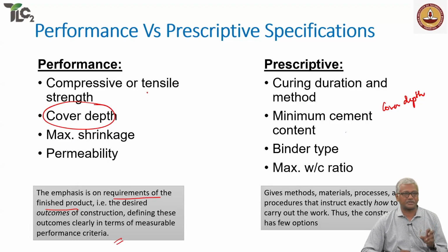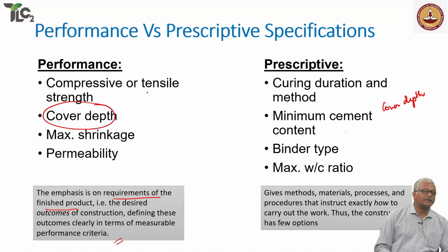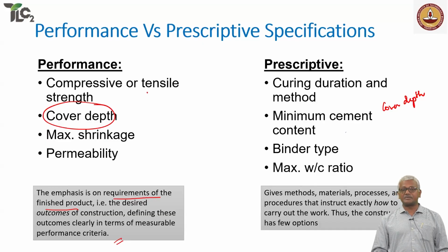How do we actually get the compressive strength? We take a core through the structure, right? We take a core and establish whether the concrete in the structure has adequate strength or not. Okay, for strength, we understand all of that, and there are acceptance criteria also that are very clearly specified in IS 456. Now, what about permeability? If at 28 days, my permeability value does not match up, what do I do? Or my shrinkage is much higher than what is given as a performance standard, what do I do? Can I do anything on the structure and measure it?